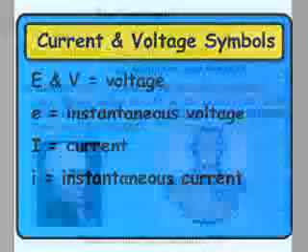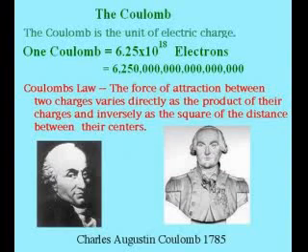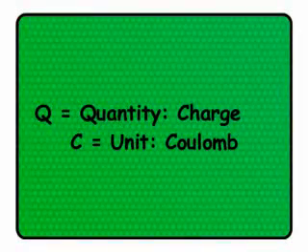One foundational unit of electrical measurement, often taught in the beginnings of electronics courses but used infrequently afterwards, is the unit of a coulomb, which is a measure of electrical charge proportional to the number of electrons in an imbalanced state. 1 coulomb of charge is equal to about 6.25 times 10 raised to the 18th power, or 6 billion billion electrons. The symbol for electric charge quantity is the capital letter Q, with the unit of coulombs abbreviated by the capital letter C.